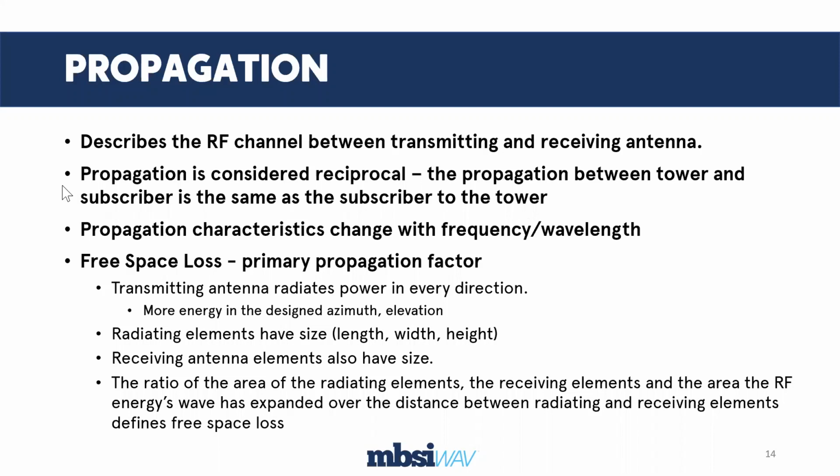As we go lower in frequency, the propagation loss reduces. That's one of the reasons why some operators use 900 megahertz in some areas, because you can still pass a broadband signal over 900 megahertz and deliver 10, 15, 20 megabits of performance perhaps down at 900 megahertz, and we have more energy that we're able to take and deliver to our CPE devices. But